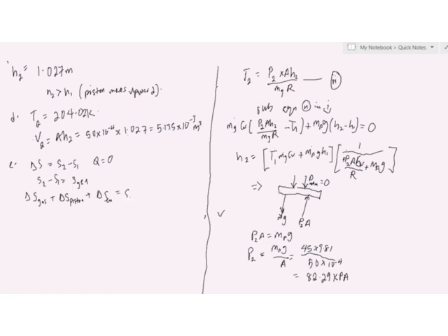All will give us our generated entropy. The change in entropy due to copper is 0 because copper hasn't made any movement. It is our piston and then our gas that actually change states. Since our piston is adiabatic and frictionless, it is also 0. So we are left with the entropy generated by the gas, which is equal to our entropy generated.